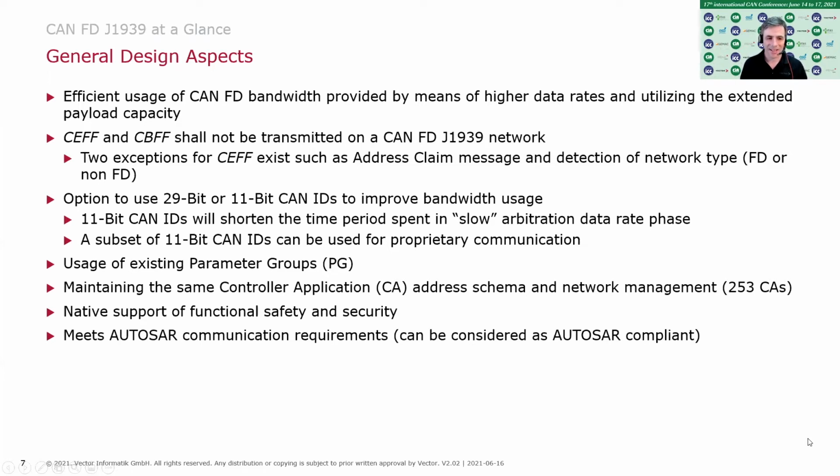The classic extended frame format and the classic basic frame format shall not be used on a J1939 CAN FD network. However, there's no rule without exception.